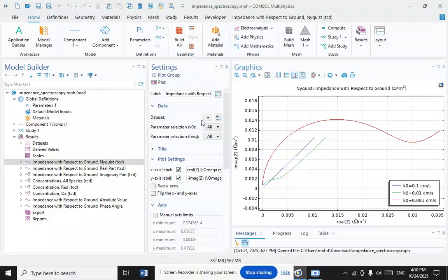These exhibit different time constants. For example, tau is a measure of the time behavior of a process. This time constant of a process is given as tau equals R times C, where R is the resistance of a resistor in ohms and C is the capacitance of a capacitor in farads. Note that the time constant is in units of time, seconds. The formulation is: 1 ohm multiplied by 1 farad is equal to 1 volt divided by 1 ampere, multiplied by 1 coulomb divided by 1 volt, which is equal to 1 coulomb divided by ampere, which is equal to 1 second.